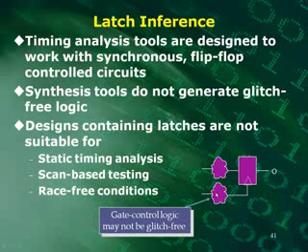You can have bad problems. What can happen is when it's switching from one condition to another, you can actually get a glitch here, a sharp narrow spike that's on this signal. And when you do that, you can violate things such as setup and hold times, and you can cause the flip-flop to go metastable. You can really screw things up. So you better be sure of what you're doing when you have gate-controlled logic, because it may not be glitch-free.